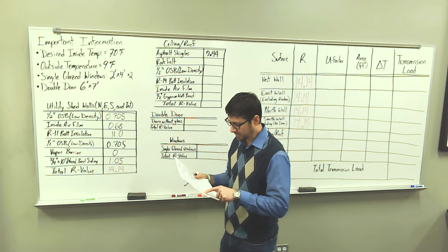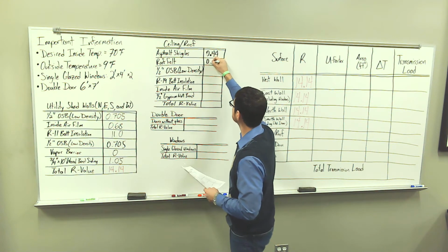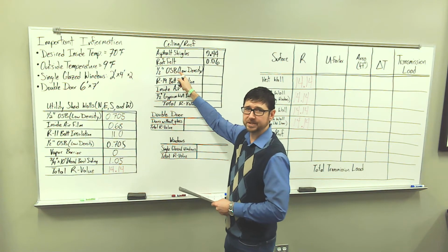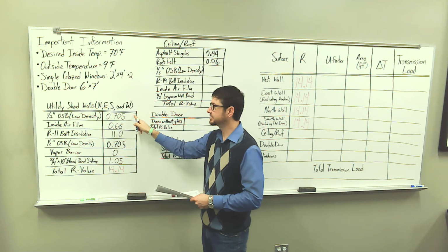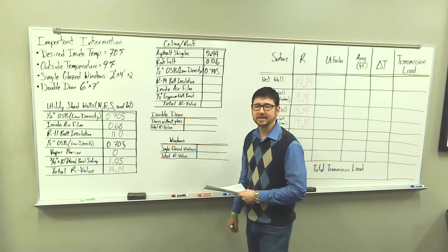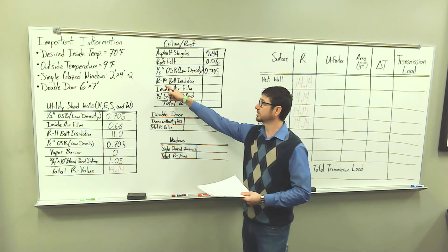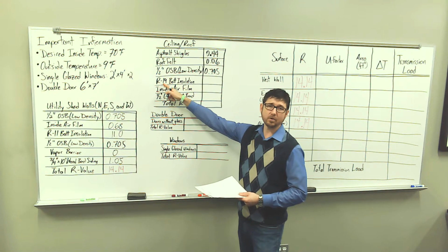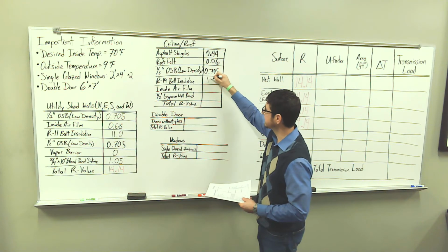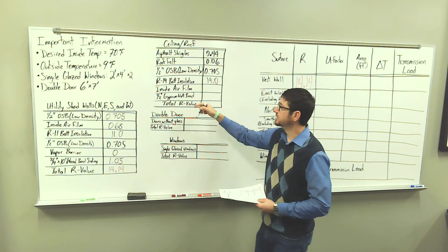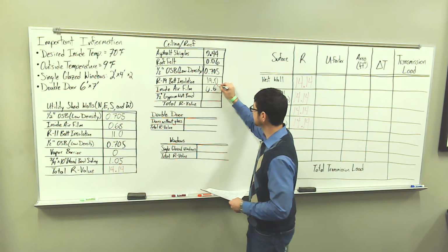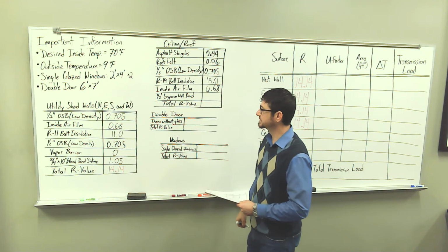Now let's look at roof felt. That's 0.06. 1/2 inch OSB, this is our oriented strand board. Well, we have this value, so 0.705. Then we have R11 batt insulation. Remember that we're going to identify the R value with its name. It's named after its R value, so this is 19. The inside air film, we have that at 0.68. And then the 1/2 inch gypsum wallboard.